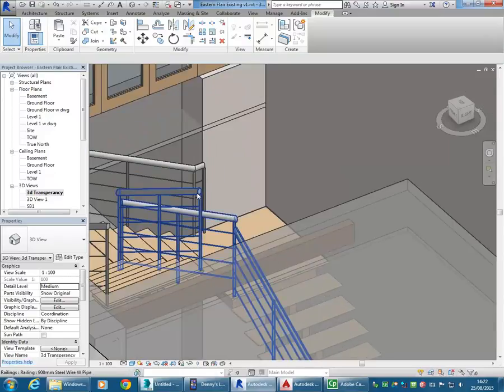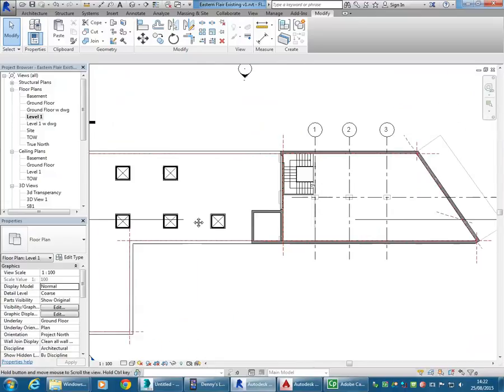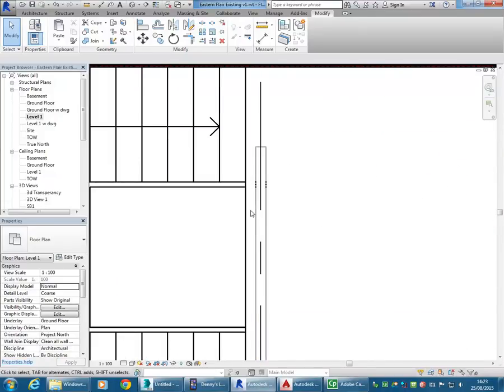If you're tempted to extend the railing over floors, it does work and it will pick up the height of the floor, but controlling the height is fairly difficult if it's continuing off a stair, so often it's easier just to add in a new railing, and that's what I'll do.